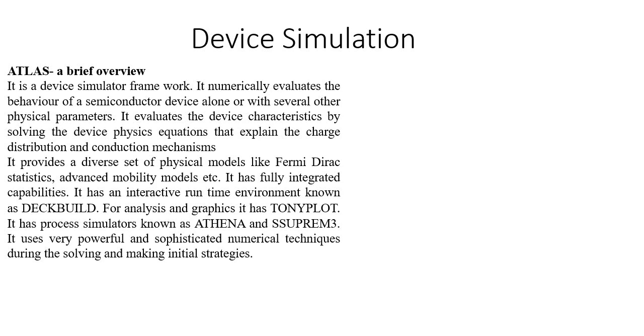It evaluates the device characteristics by solving the device physics equations that explain the charge distribution and conduction mechanism. It also provides a diverse set of physical models, like Fermi-Dirac statistics and advanced mobility models like the Philips model and the Lombardi model. So all these mobility models are present in the Atlas simulator.